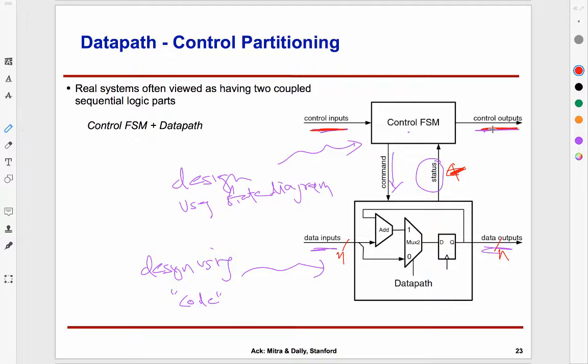You are actually going to be seeing this for a whole bunch of clock ticks. So usually you will have to do some additional things. For example, depending upon the keyboard, it may say normally all the wires coming out of the keyboard are high, and whenever a key is pressed, it goes low. Let's say a very simple keyboard. For every key, there is a wire coming out. So if I have 100 keys, there are 100 wires coming out. But those wires by default are high. When the user presses a key, the wire goes low.